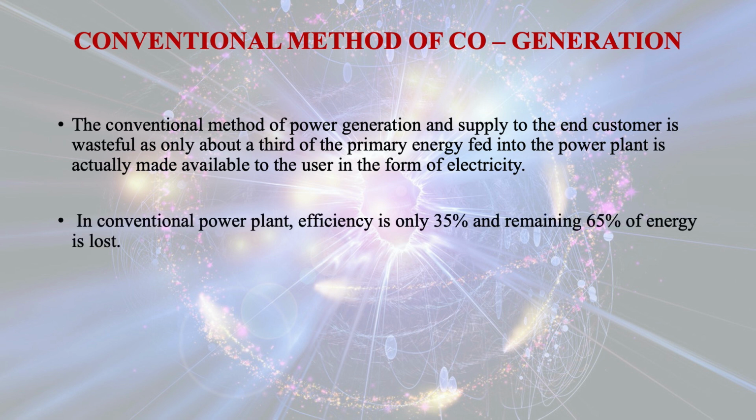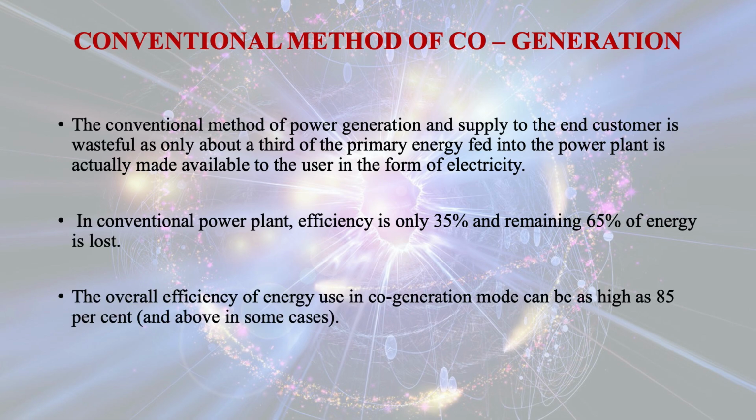Then 1 minus m1 kg of water is pumped to heater 1, where it mixes with m1 kg of steam extracted at pressure P2. The resulting 1 kg of water is then pumped to the boiler, where heat from an external source is supplied.